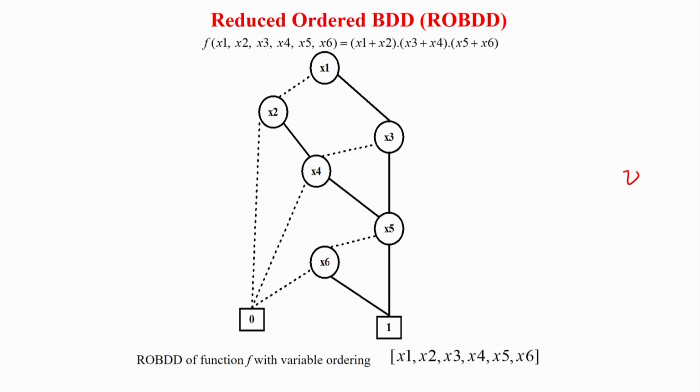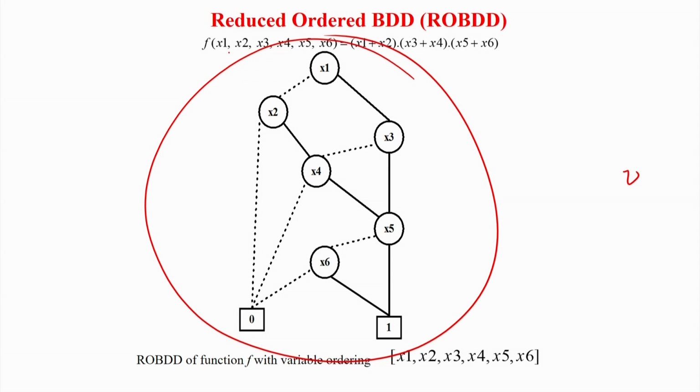So as it is very much compressed, in some paths some of the nodes will not be there. That is obviously the requirement when you are going from binary decision tree to binary decision diagram. But in no path you will find the order flipped. So in this case the ordering is this, and if you draw the binary decision diagram, which you can take as homework, you will find out that this is the size of the tree.